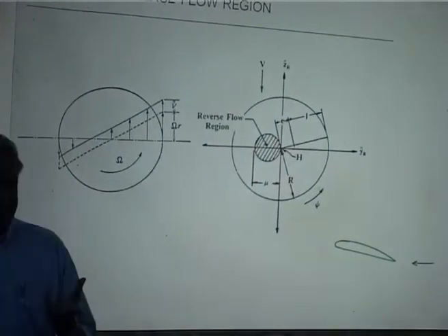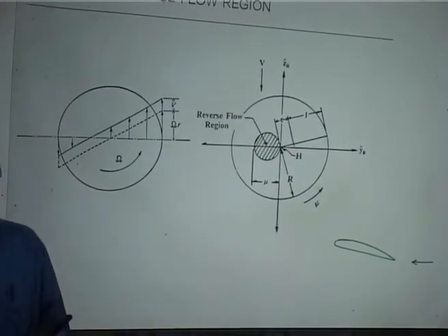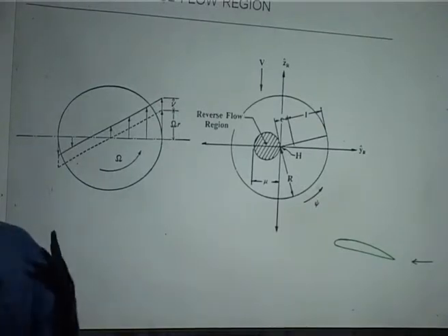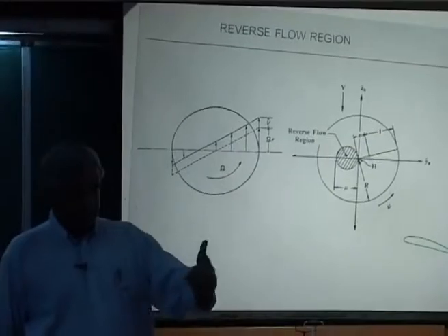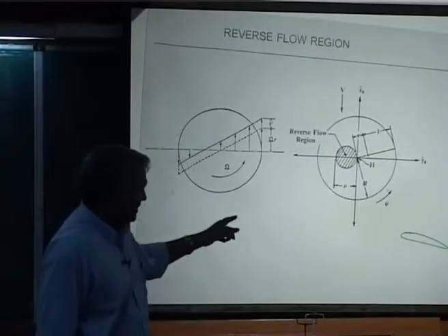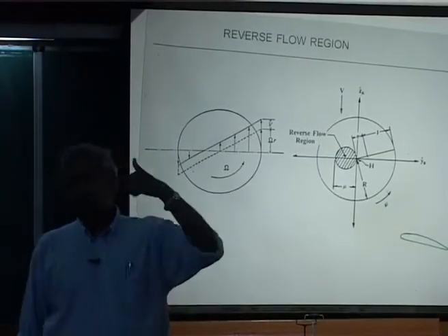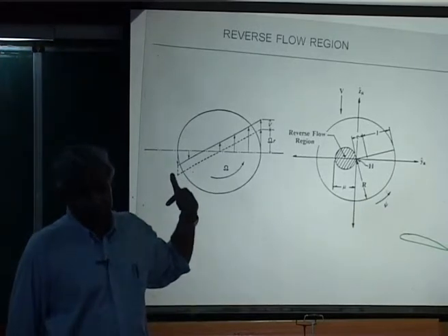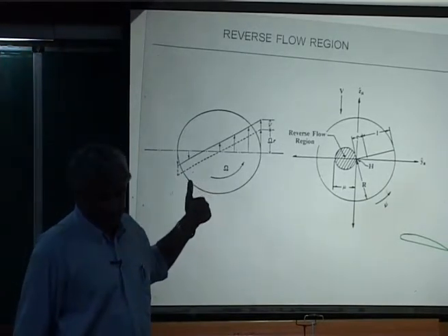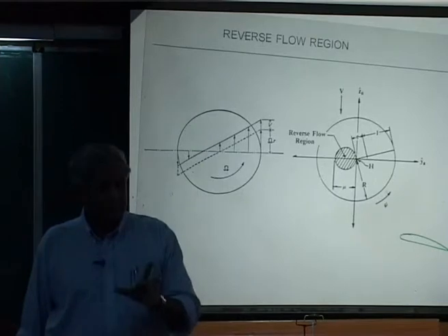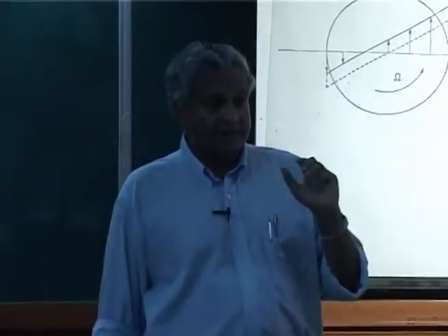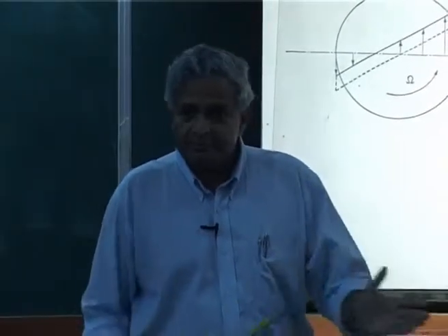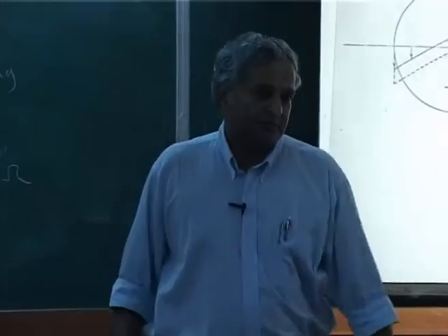And some of them may not be very effective sometimes. And you have to know the aerofoil characteristics, in terms of CL, CD, etc., when the flow is coming from trailing edge to the leading edge. That means you have to do an internal test. But these are all a lot of aerodynamic characteristics of the aerofoil, they are required when you are actually making the blade.